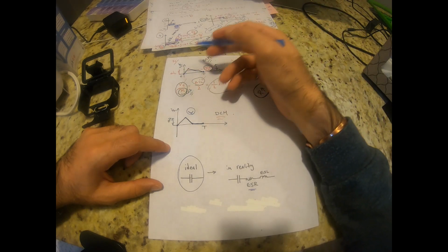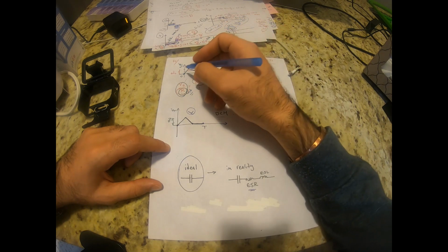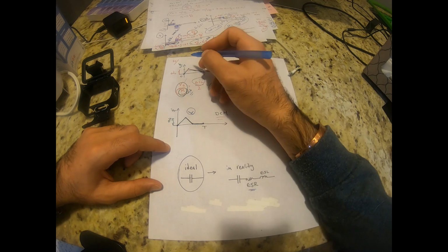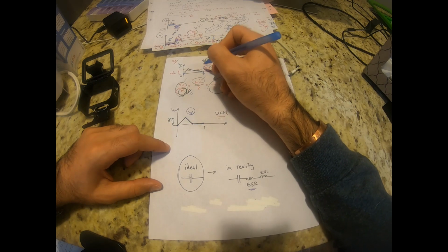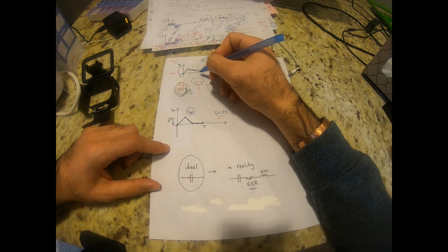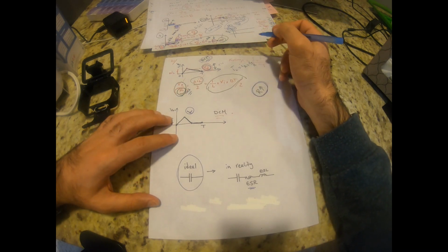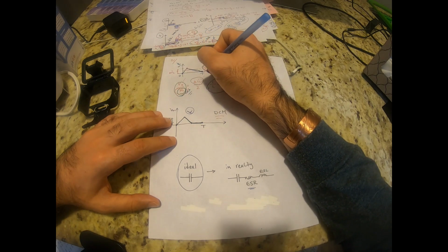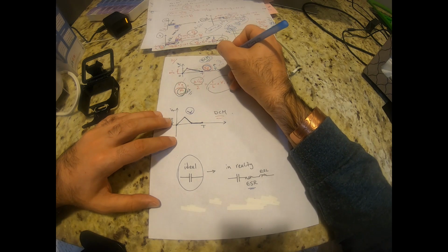But before we get to this point, as you increase R, you get to a point that your inductor's current starts from 0, goes up to delta IL, and reaches 0 at this point. This is called boundary conduction mode. It means that current gets momentarily 0 but it doesn't stay 0. In this case, the average of IL is going to be VO over R, and it's equal to delta IL.